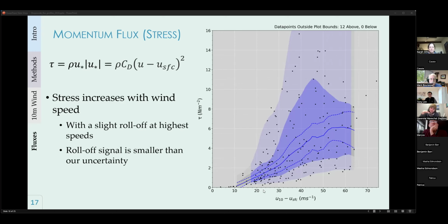But once you get a displacement height that gets to be more than 2/3 of the height of the sensor on the buoy, you're not really taking observations from a log layer. And that's a fundamental assumption for doing those calculations. So under those conditions, I'd get nervous.